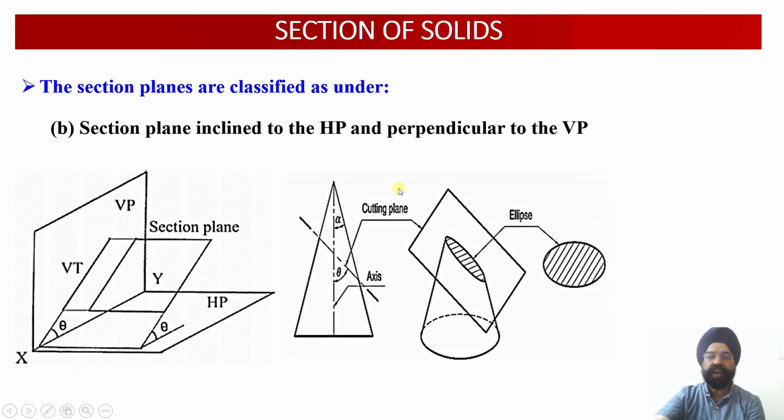And now you see, since the solid has been cut by a cutting plane which is AIP, this portion we are going to throw out. If you look at the cut surface from the top, its projections obtained on the top view will give us the apparent projections. So whatever projections we obtain in the top view, we are going to say: draw the sectioned top view.